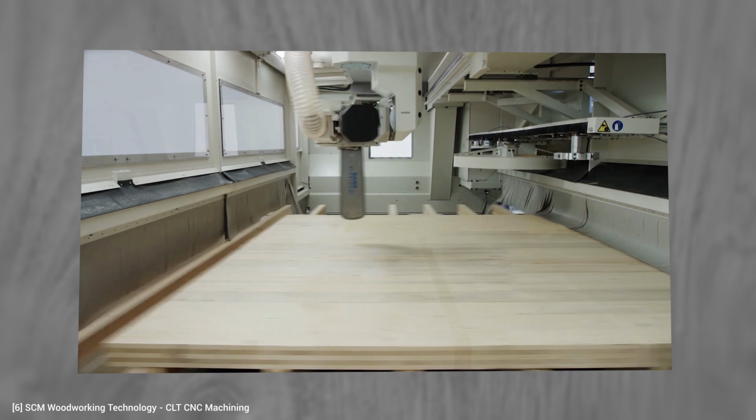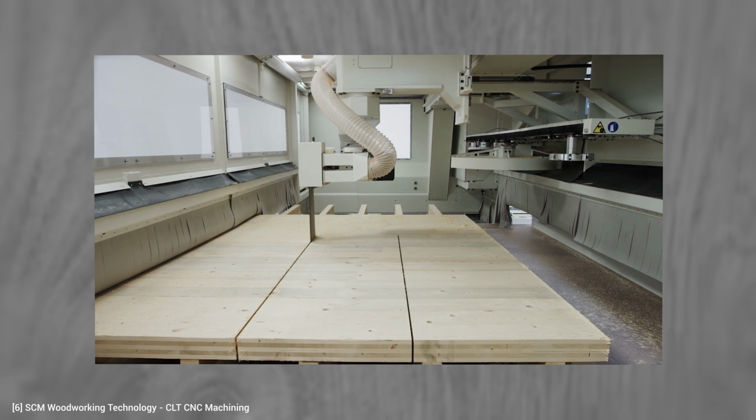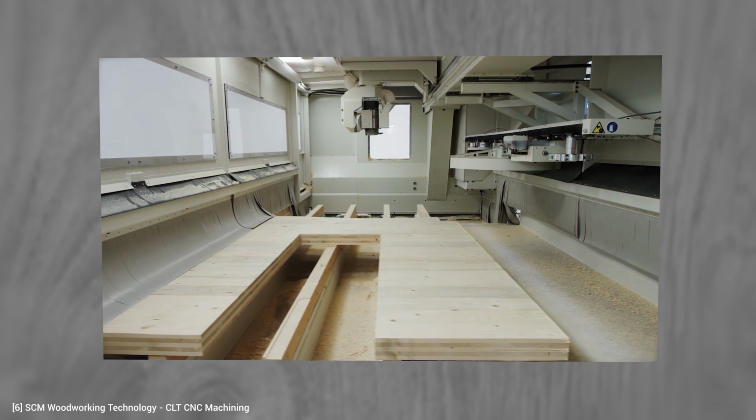The finished CLT panel gets sent to a CNC machine, where any windows, doors and other openings can be cut into the panel. For every CLT panel, pieces that are cut out by a CNC machine get tested to make sure that every panel is safe to use. If necessary, any metal fasteners or anchors can be applied to the CLT panel in the factory to make construction on-site even easier. The most commonly used fasteners are traditional or self-tapping screws, nails, bolts or dowels.